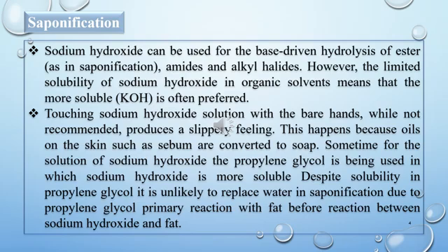Then we have discussed the mercury cell process, in which the cathode was formed of mercury and sodium dissolved in mercury, which formed sodium mercury amalgam, and after that, by the decomposition of sodium mercury amalgam, we have separated sodium and mercury. Then that sodium reacts with water and forms sodium hydroxide. Similarly, we also have discussed why we prefer the membrane cell process as compared to the diaphragm cell process and mercury cell process.